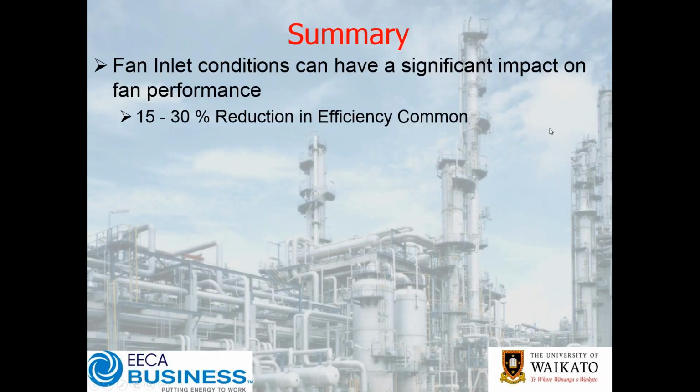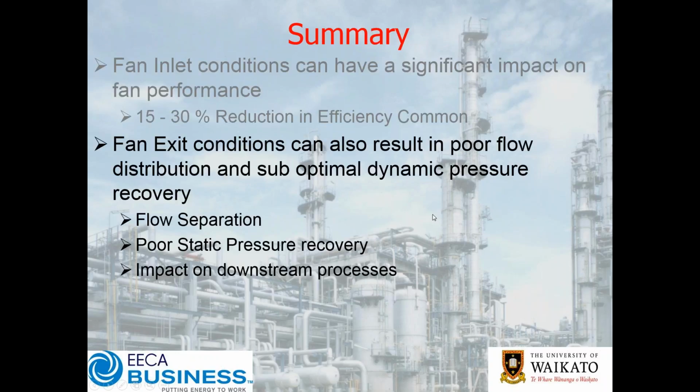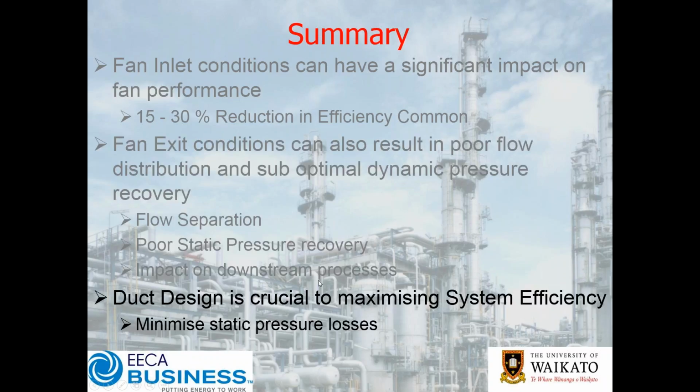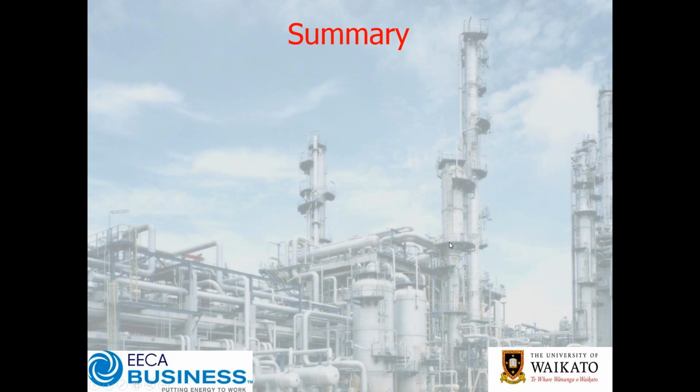So in summary, to finish off today, the fan inlet conditions can have a significant impact on fan performance. 15 to 30% reduction in efficiency is not uncommon or unheard of. Fan exit conditions will also result in poor flow distribution and suboptimal dynamic pressure recovery. You'll get flow separation, okay, and will impact on downstream processes. Duct design is crucial to maximizing system efficiency and minimizing static pressure losses.